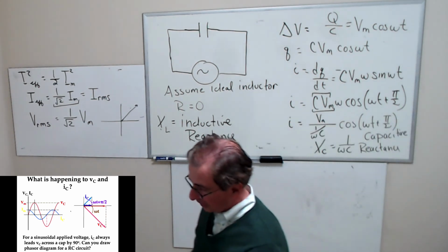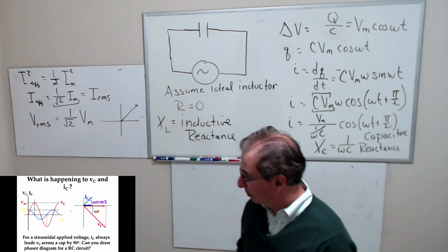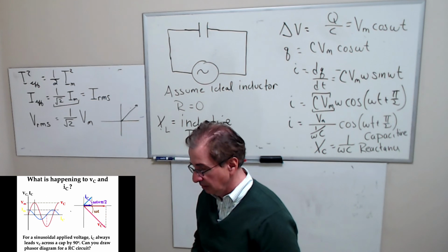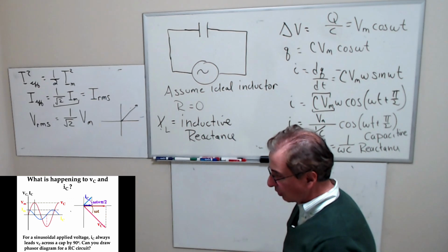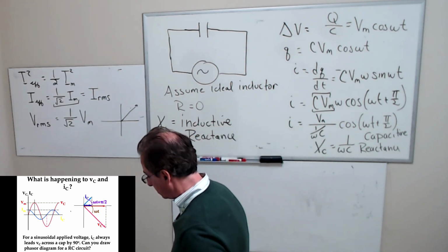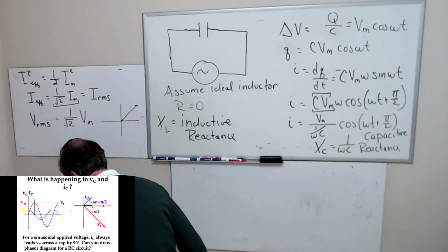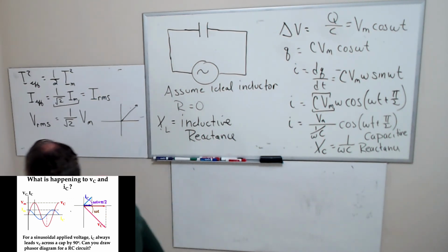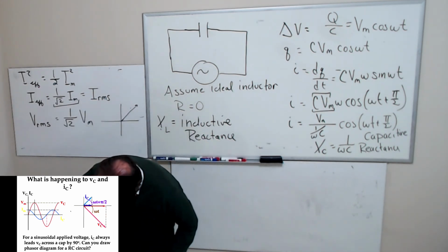So the question is, can you draw a phasor for an RC circuit? I think you'll be able to draw it once I do the RL circuit, which I'll do on Monday. Okay, so let me show you an example of an RC circuit. This is not truly an RC circuit because I actually have a resistor in my circuit, but I'm cheating. But if I set this frequency correctly, you'll notice the 90-degree phase shift.